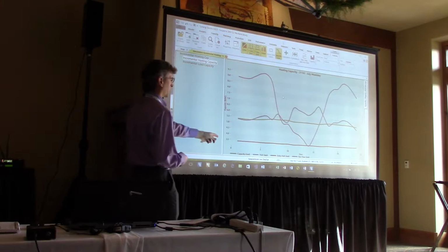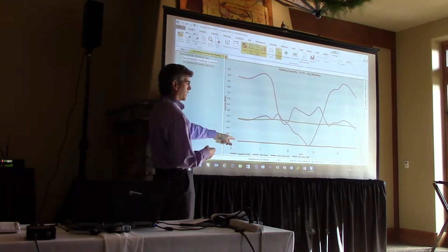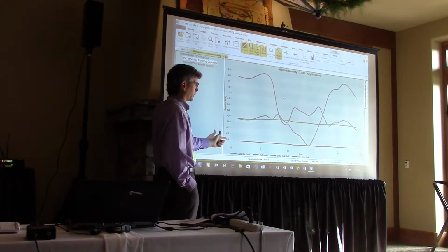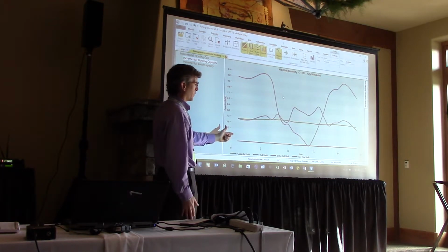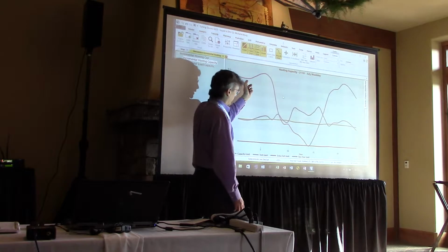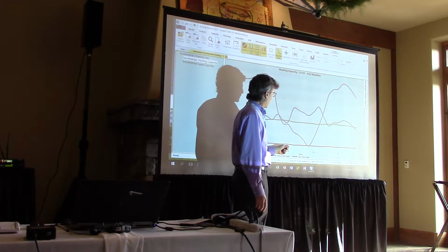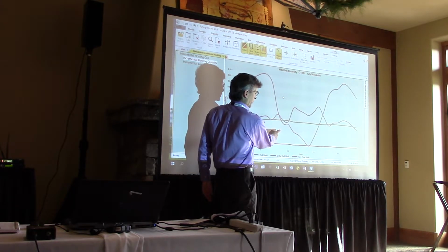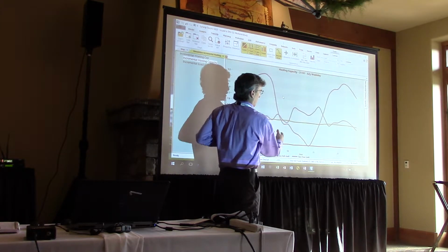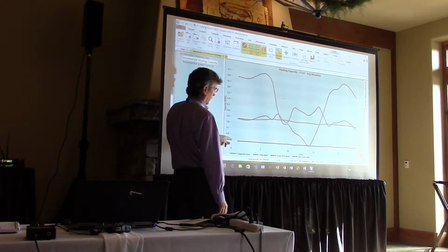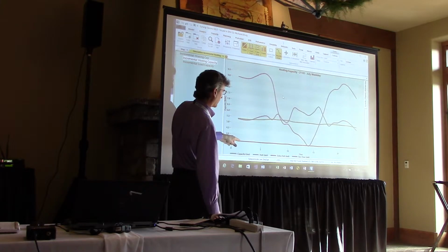Just want to make it clear that we're talking about intermittency here. So if that PV generator were to kick off, how much change in voltage would the customer see? And so if I get to 3.5 megawatts on that section, any more than that is going to hit my voltage violation. And this curve right here is reverse power flow. And you can see how it almost dips down. Sometimes it's pretty cool. We'll try some different locations, but these things start to overlap each other. So sometimes this will dip down, but here the only factor for this location looks like it's delta voltage.